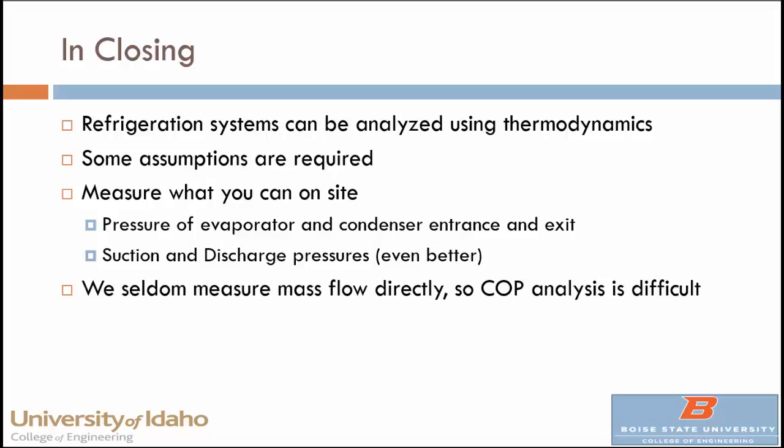And just one last thing, it's really hard to know mass flow rate. Mass flow rate meters are expensive. They're kind of fussy, and so we don't generally use them in industrial settings. And yet this would be probably the most useful piece of information. So anything we can do to kind of deduce mass flow rate is very valuable.